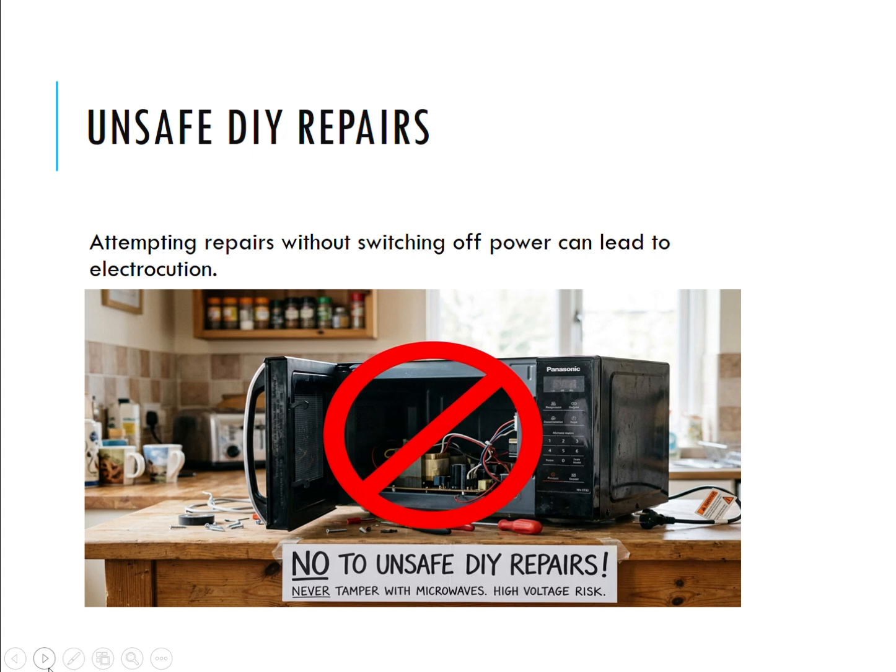And again, when it comes to microwaves, even if they are not powered, they have a lot of capacitors in them. If you attempt to fix them and do not properly discharge those capacitors, you have a very high risk of getting severely shocked.